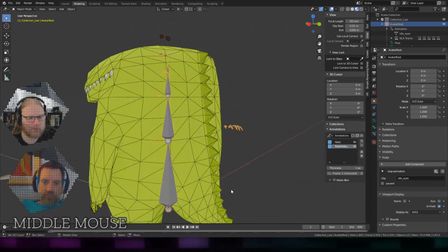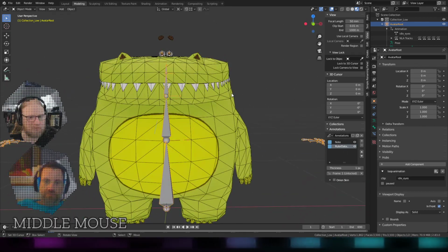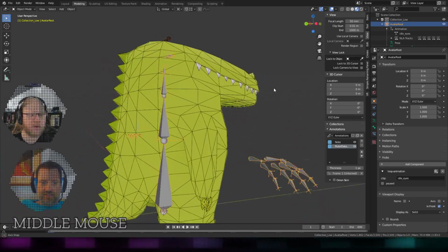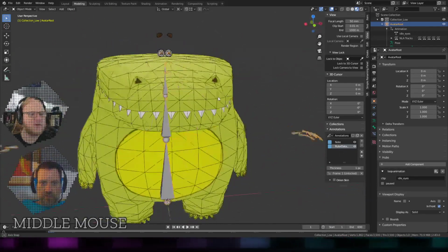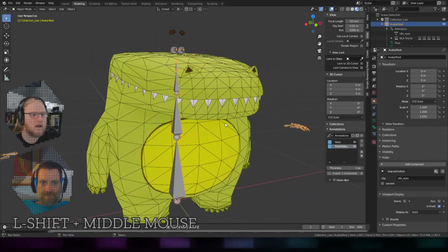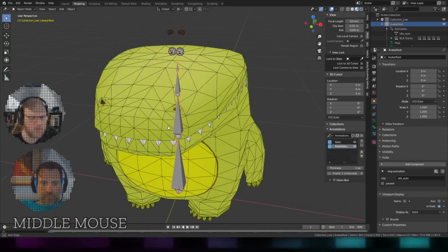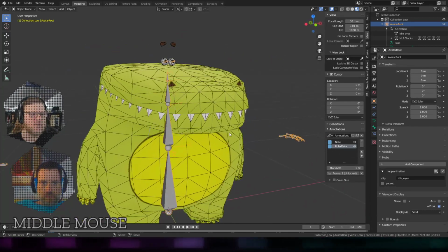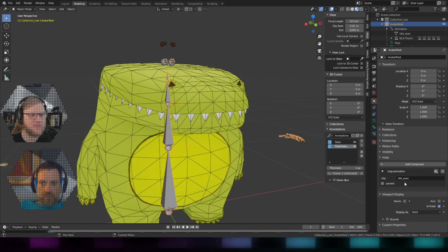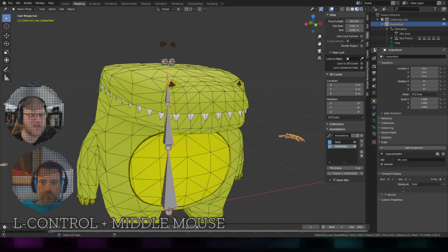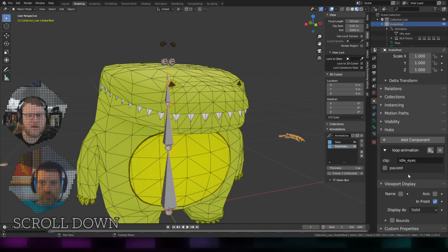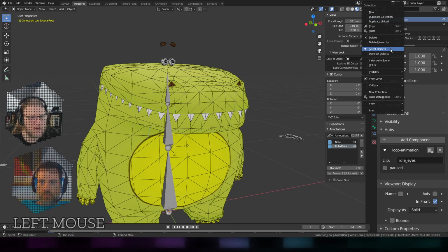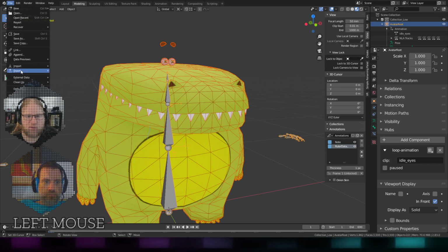Now, if I had a tail moving idle animation, or maybe his little fingers move, like a little breathing. A tail wagging one would be pretty cool. And that's a good point to bring up actually. You can totally have extra bones in this. Hubs doesn't care. We have seen people create avatars with tails and use those bones to animate it, and that's totally fine. Hubs really only, for the most part, cares about the head and the hip joint right now. It doesn't actually even care about the hand bones. As we're looking into hand tracking, the finger bones are probably going to matter, so it's best to keep the same names as we have in here right now.